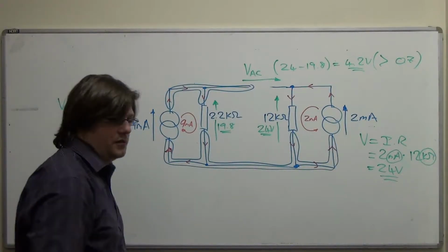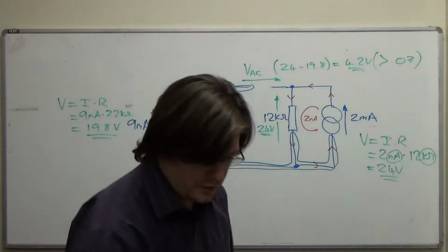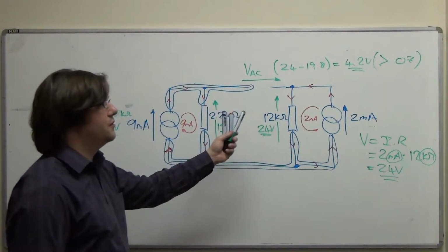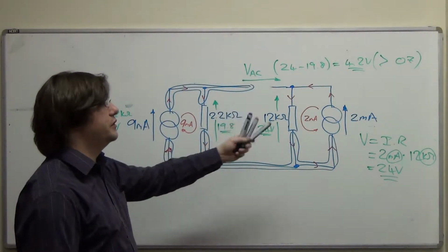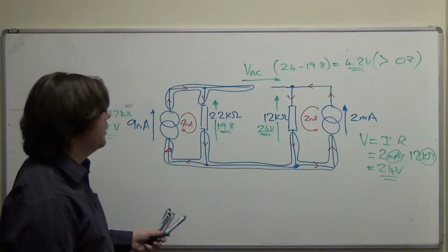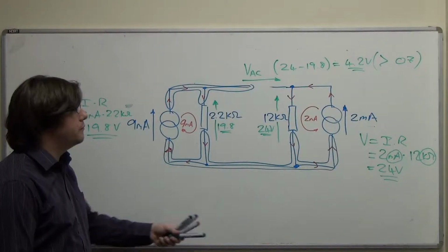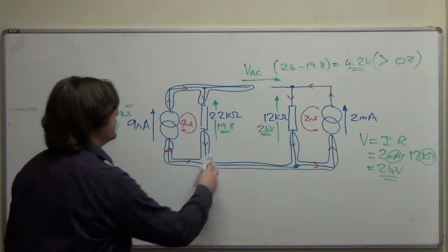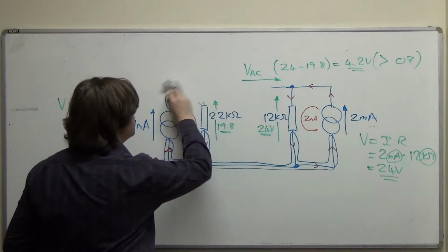And then we have to do the same thing we always do at this point. Change the circuit so the diode's in it, assume 0.7 volts because that's, well, we don't assume it, we know it's conducting, and if it's conducting we know that we're 0.7 volts across it. And then we'll redo the calculations. So I think I'll redraw it.